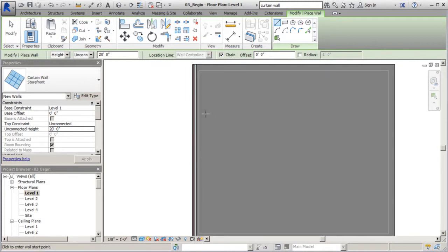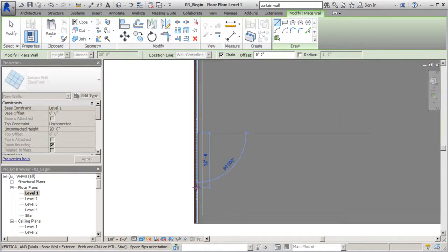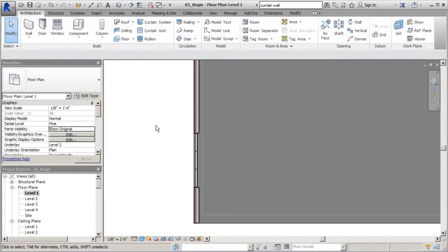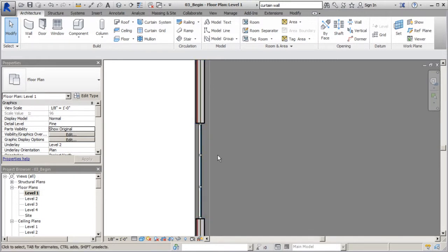So if I want to get this guy placed, I'm going to do it within a wall. And if you remember from the last lesson, because I have automatically embed checked, and it's also checked by default, I can come over this wall and draw over it. And I'm not going to get that warning signal that tells me that I have two overlapping building elements in place. Because what happens is, drawing that wall in place automatically embeds it inside that wall system, creating the cuts I need to fit this guy within that opening.